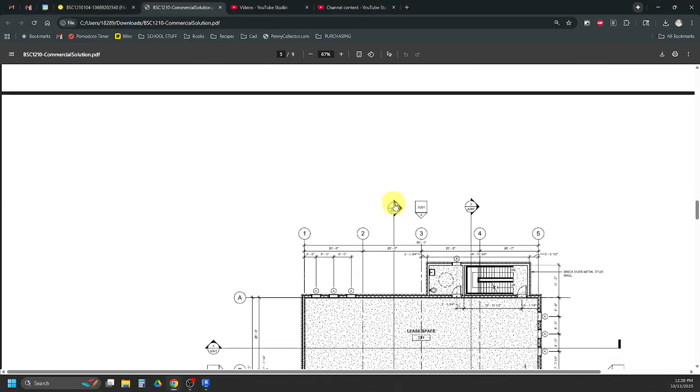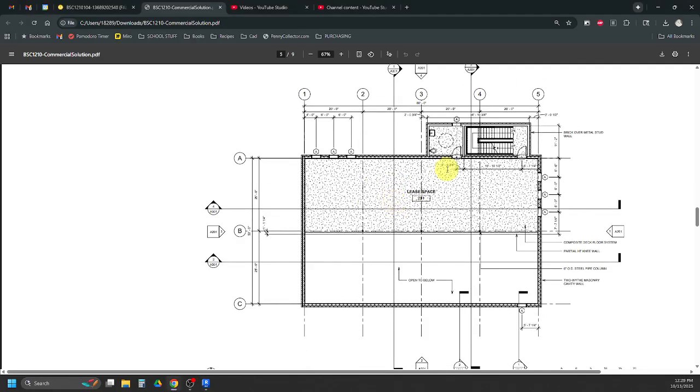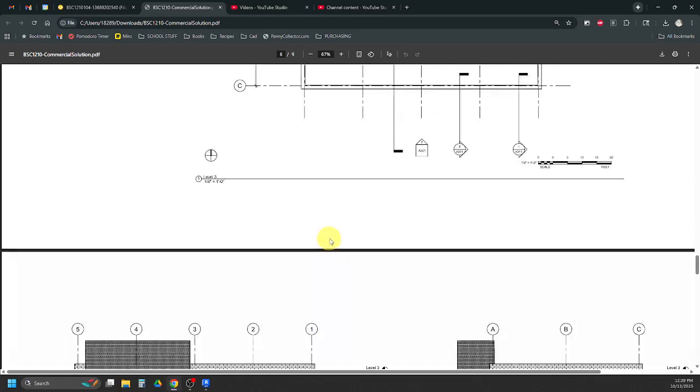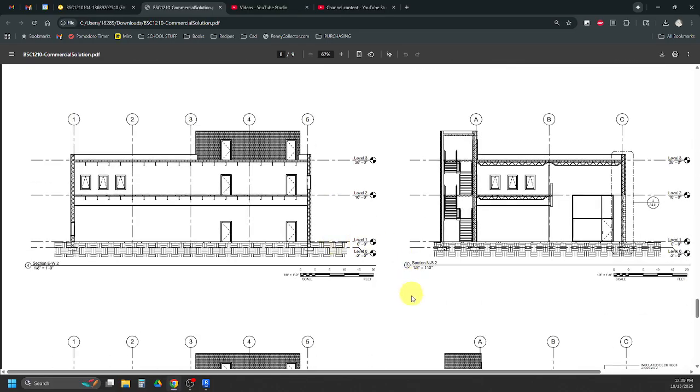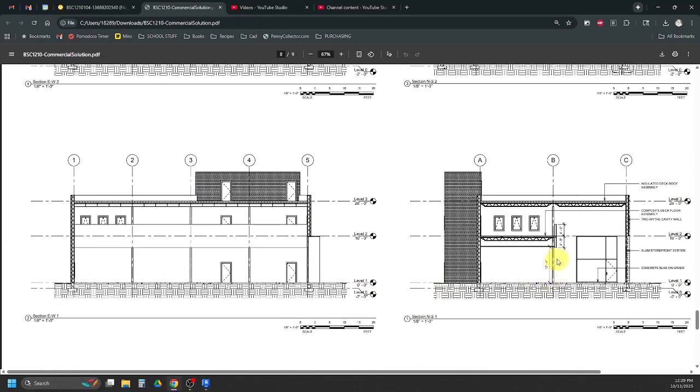So my level 2 floor is going to be made out of a different material, but we also need to put in our partial height knee wall here as well. So I need to put that wall in first. Now that wall, if we go look at it in section, starts 4 feet underneath level 2 and then only goes up 4 feet.